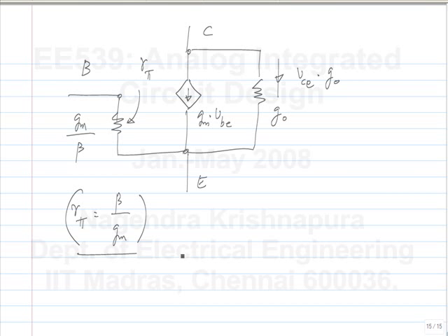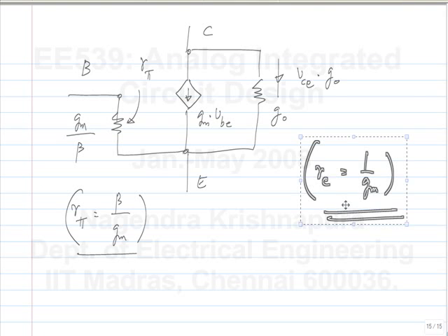Okay. So this is the model of a bipolar transistor. This is the model we will use. If you read older textbooks on bipolar transistors, you will have the model with RE or lowercase re, which is basically the reciprocal of gm. Okay. We won't use that. We'll use a model that is similar to the MOS transistor model, so that our analysis carries over between MOS and bipolar circuits. Okay. And this model also we find is more convenient to use than the other model.